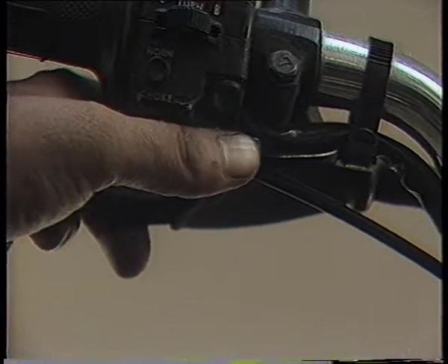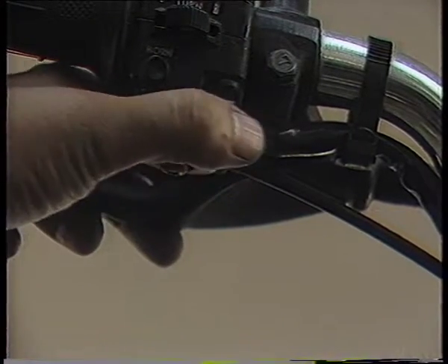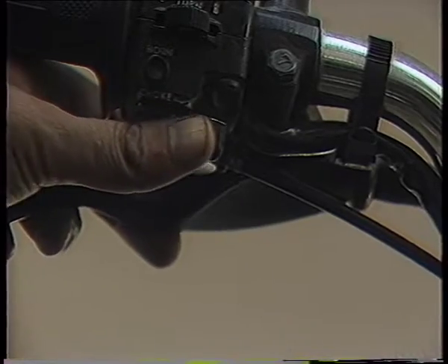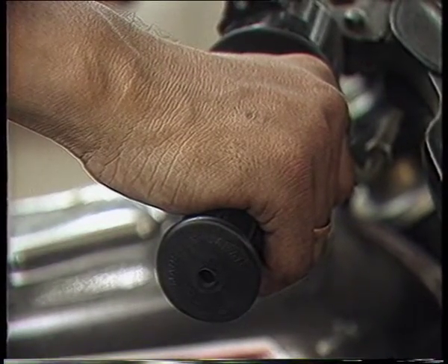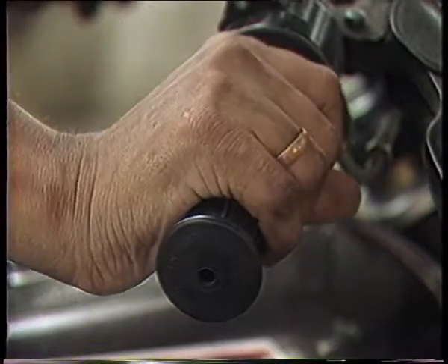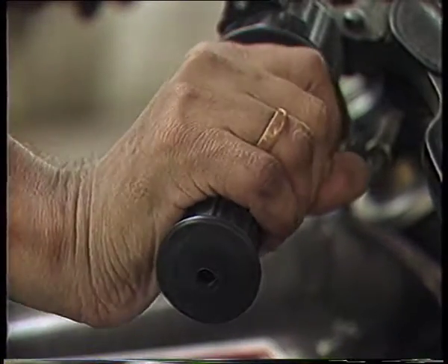I hope that by now you have understood the basic functions and designs of carburetors. But to complete a full circle of this knowledge, we must look into the area of troubleshooting related to carburetors. For example, if the engine fails to fire from the cold, what faults could be responsible? The cause may be an excessively rich mixture. This can be the result of prolonged use of the choke control. Pumping the accelerator in the endeavor to start will also cause a rich mixture.